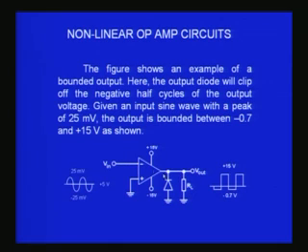If you measure, the input is a sine wave of about 25 millivolts peak amplitude. That is enough for us, because we require only plus or minus 150 microvolts above 0, and one of the inputs is connected to 0. Therefore, it is a zero crossing detector now, and when the input goes beyond 150 microvolts or so, the output will become minus VCC.